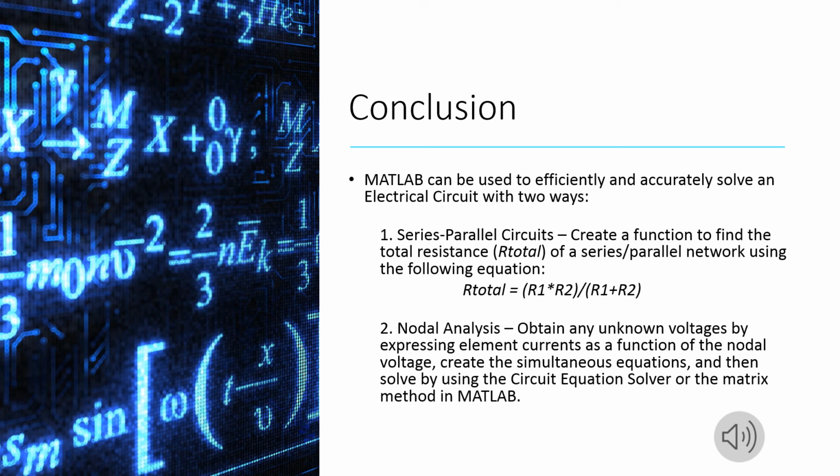For this, we can obtain any unknown voltages by expressing element currents as a function of the nodal voltage. Then we create the simultaneous equations and then solve them by using the circuit equation solver or the matrix method in MATLAB. We could also solve these by using a calculator. However, these methods would not be as efficient as using our MATLAB programs that we talked about today.